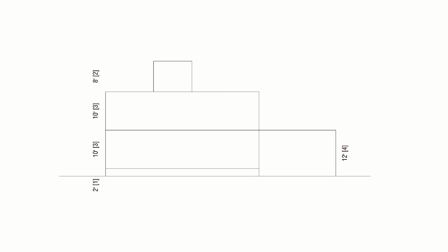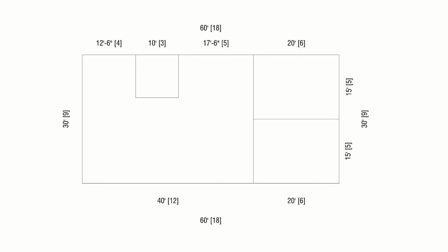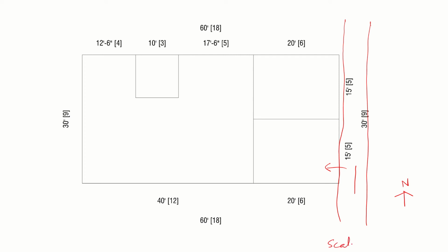And we have also drawn elevations. I see many of you are making errors in the drawing. When you draw a plan, kindly mention a few things which are not there here as well. We need to show, let's say if this is the street or the road from which the site can be accessed, mention the site. Mention north. Mention somewhere the scale in which the drawing is made. These are essential things.